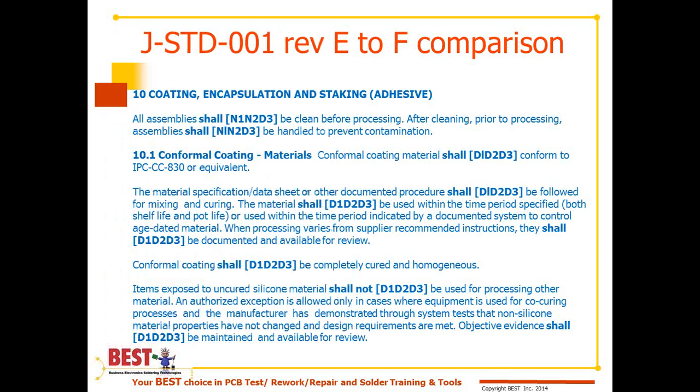And when processing varies from supplier recommended instructions, they shall be documented and available for review so that we can see what's happening, and that's a defect if it's not. The conformal coating shall be completely cured and homogeneous, which is completely mixed.